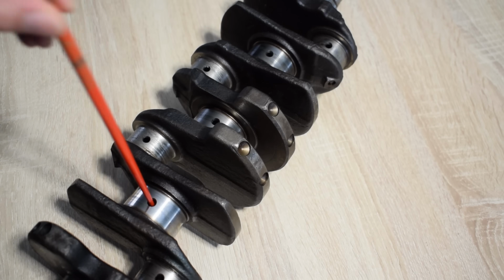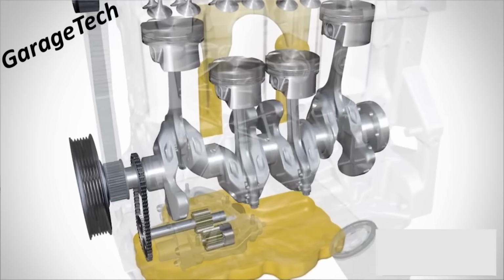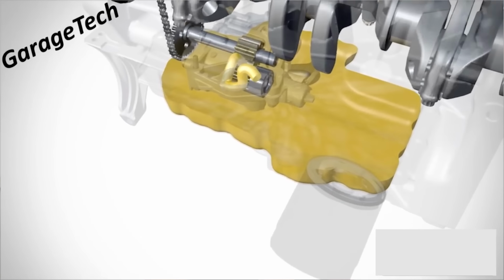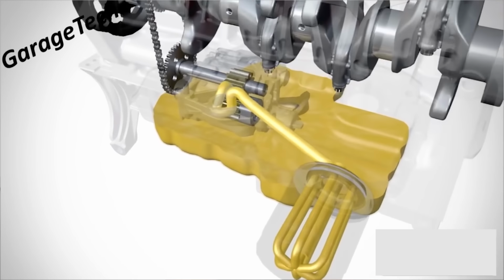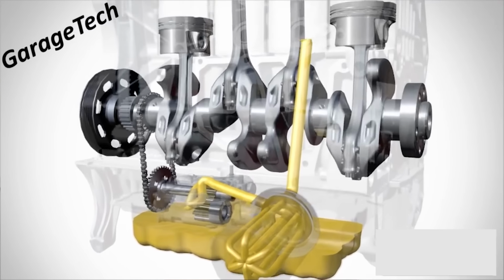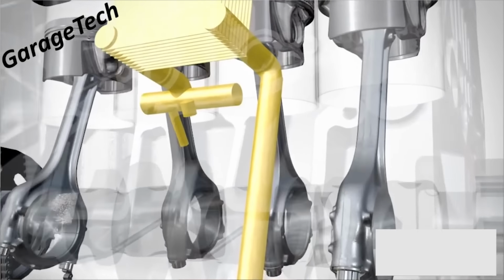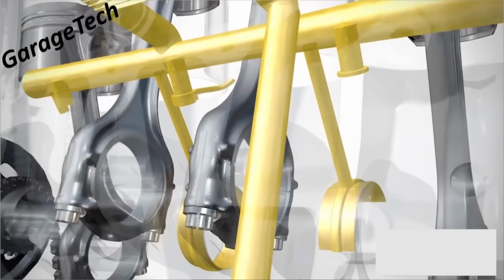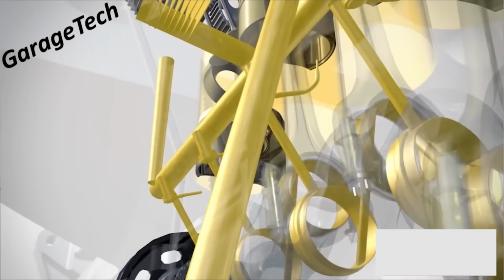Now, the holes that you can find in the rod and main journals are oiling holes. Engine oil is picked up from the sump by the oil pump and sent through the block to the crankshaft. The oiling holes on the crankshaft have the task of creating a film of oil that prevents metal-to-metal contact between the crank journals and the rod and main bearings.